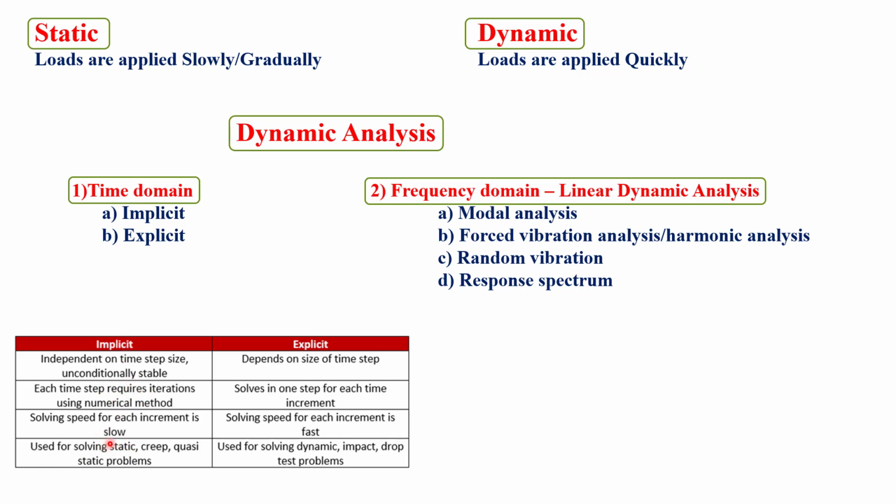So for that we don't use it much, but some analysis is needed for quasi-static problems like metal forming and creep analysis. We use it here, and for some of these static analyses. For explicit we use it extensively, and for dynamic problems like impact, crash, and drop tests, everywhere.